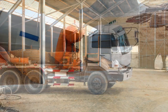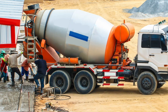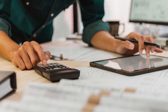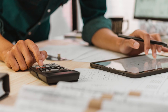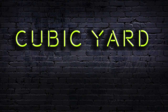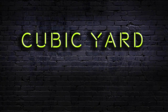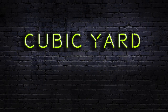concrete project. Most large projects will be delivered by a ready-mix concrete company that will price the concrete by the cubic yard. Calculating the cost for a concrete pour will basically become a volume calculation that needs to be converted to cubic yards. One common way to calculate the volume of concrete is to convert all measurements to cubic feet and then convert that measurement to cubic yards. Understand that there are 27 cubic feet in a cubic yard.